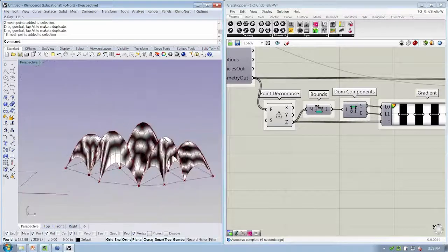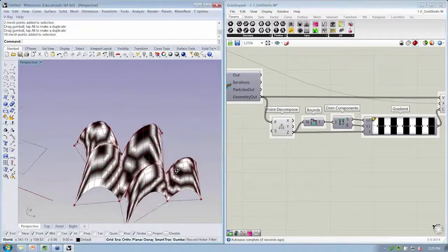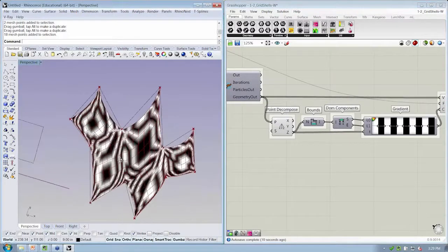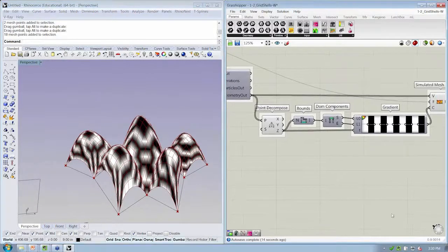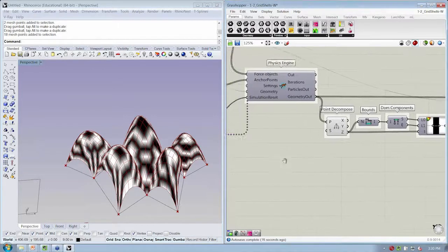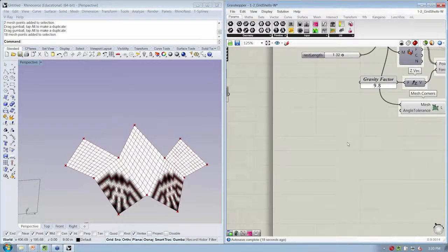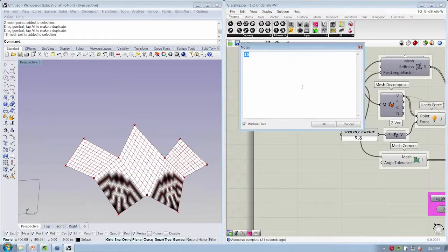That's fun. And if you want a finer quality to your mesh, because it's trying to smooth out the difference between all the colors, we block our slider, set our simulation, and go higher with our mesh divisions. Now remember, this is kind of exponential. It's going to increase dramatically how many mesh divisions we have.